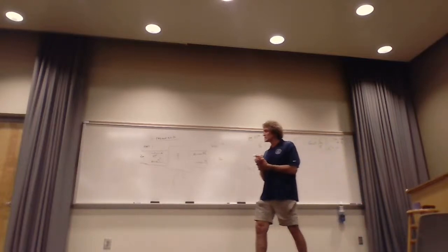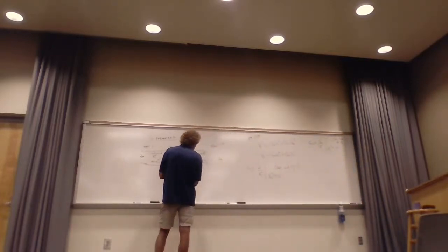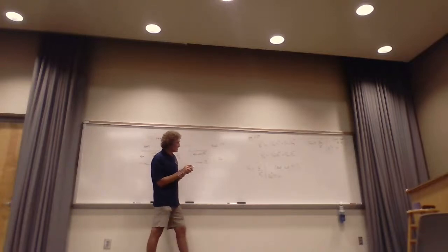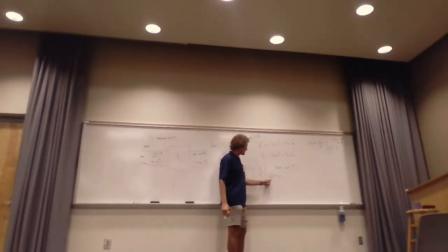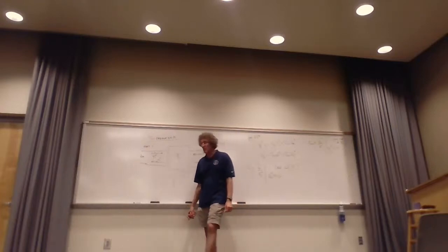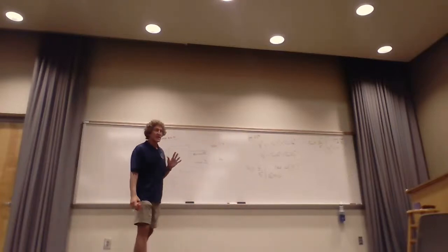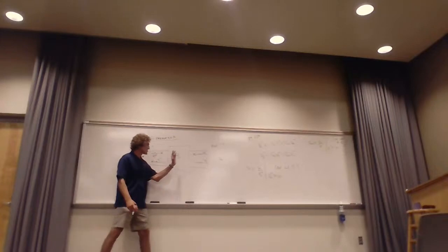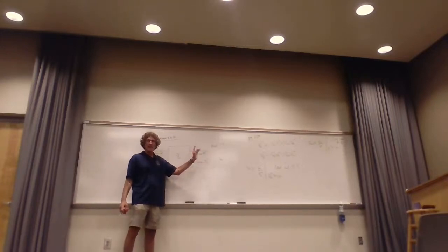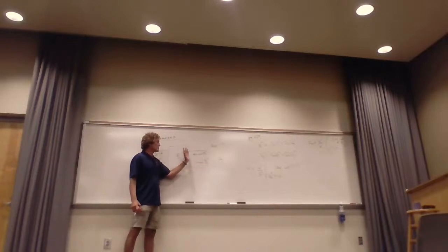And it assumes, now I got to tell you one other thing. You see how I said here that for S11, assuming V2 plus is 0, I want to make sure you see one thing. In order for that to be the case, that's a transmission line, right? Well, if you had a short there, then the outgoing wave here would reflect back.